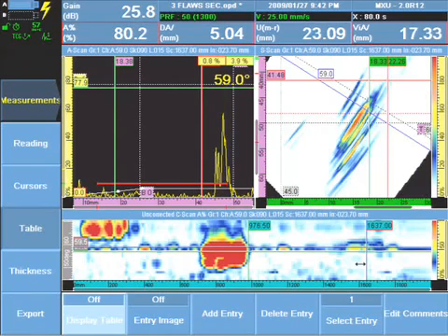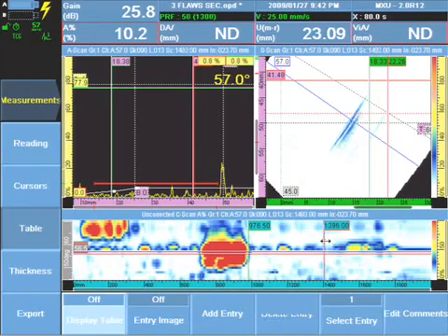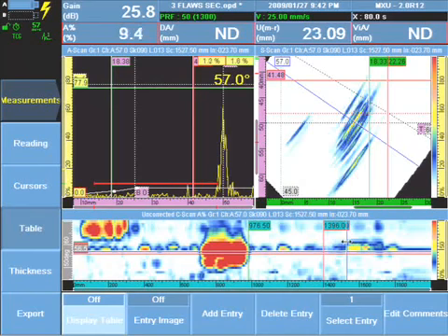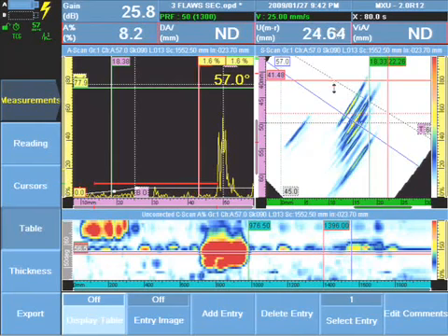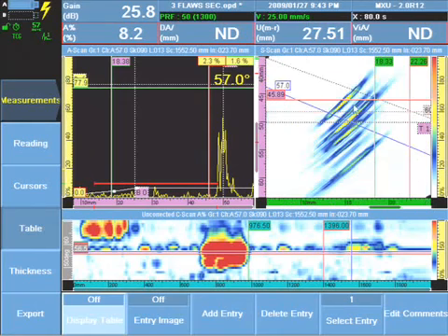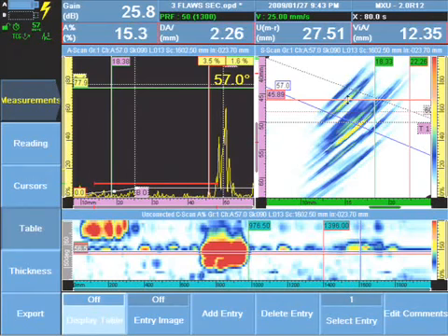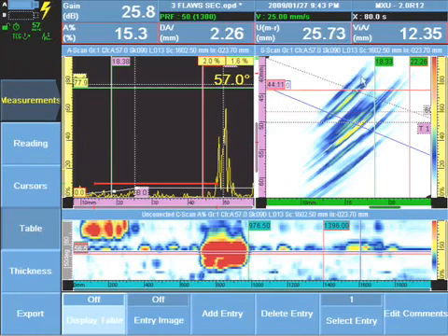We will identify the start of the crack on the scan axis. We'll walk through the crack, identifying the center of the deepest tip diffracted signal we can find, and as I move my cursor, every time I see a deeper tip, I'll move my cursor to the center of it. We're only interested in the center of this energy.